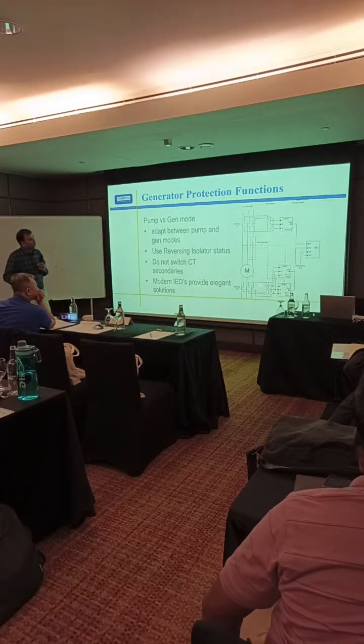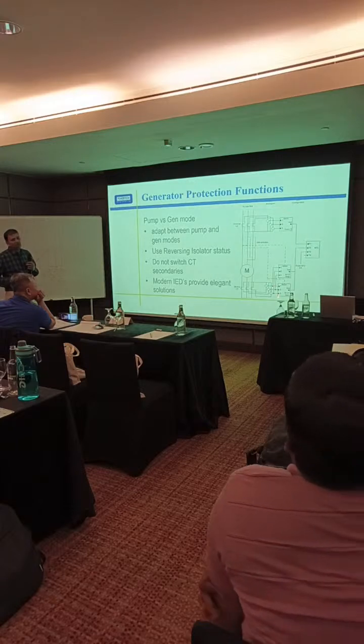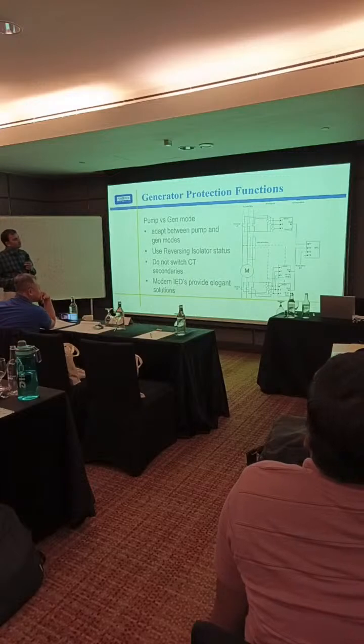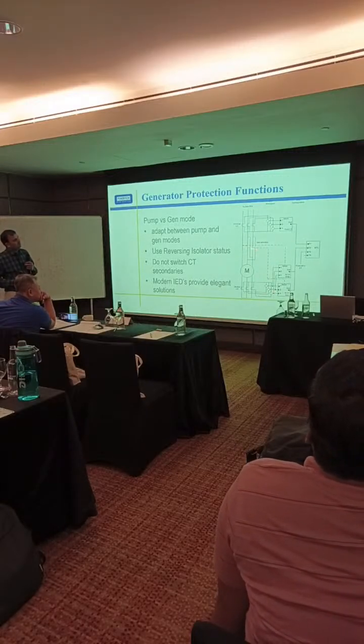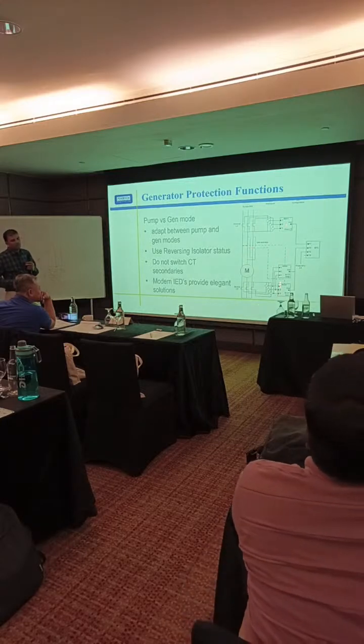This is the blocking option. It is just an example. Different blocking options are implemented in the relay, so that during pump mode, this isolator may change and the differential protection is blocked in this case.